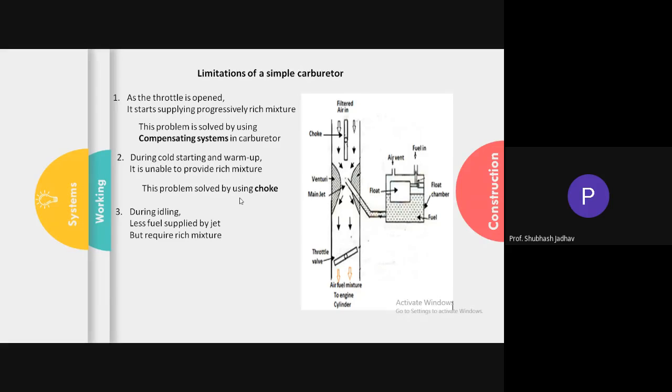You have started the engine, but you are not running the vehicle. Your accelerator is at 0 position. Okay, then you will call it idling. So very slowly the firing will take place. Duk, duk, duk, duk, duk. Our aim is just to provide that much energy to sustain the firing. That means we want the firing to continue and the engine to keep running, so only that much power is expected to be produced.